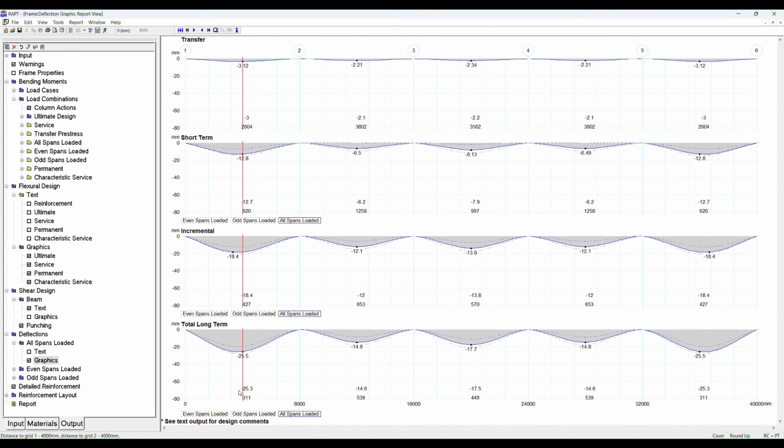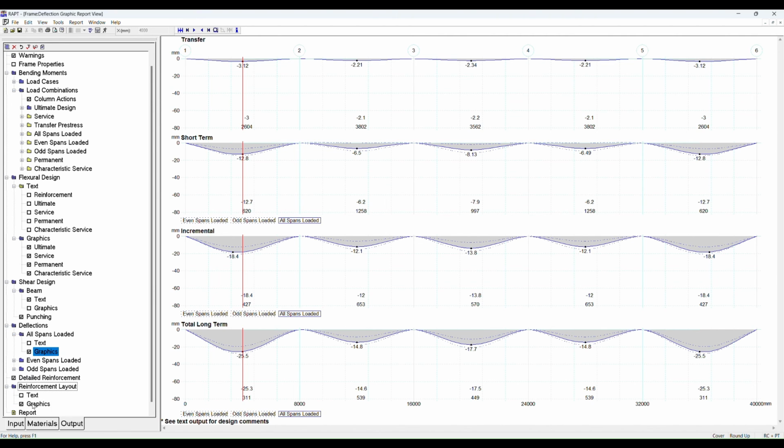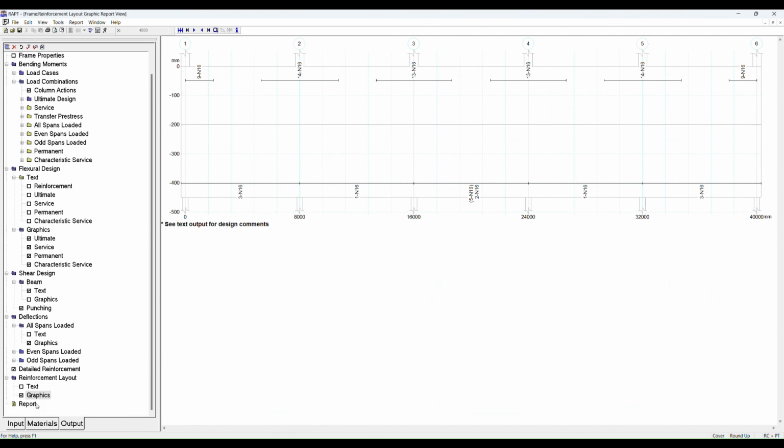The deflection given down here is deflection from this point to a straight line at the top of the column here to the top of the column over there. And the span to deflection ratio is based again on the deflection relative to the tops of the columns. So that deflection is calculated based on the minimum amounts of reinforcement that RAPT has calculated as being required to meet code requirements. Then RAPT has also laid out additional reinforcement as one solution to meet those minimum amounts of reinforcement.